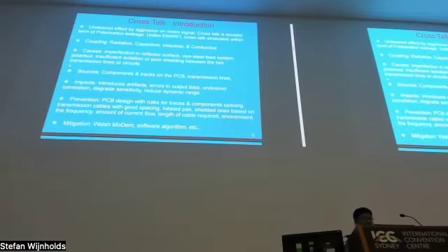First one is crosstalk. Crosstalk is an effect of the aggressor signal over the victim signal. Crosstalk is a broader term than polarization leakage. Unlike EMI and RFI, crosstalk emanates from within. This crosstalk is coupled either radiatively, or in capacitive, inductive, and conductive ways. The causes are imperfection in the reflector surface, non-ideal feed system, polarizer, and insufficient isolation or poor shielding between two transmission lines or circuits, meaning PCBs.